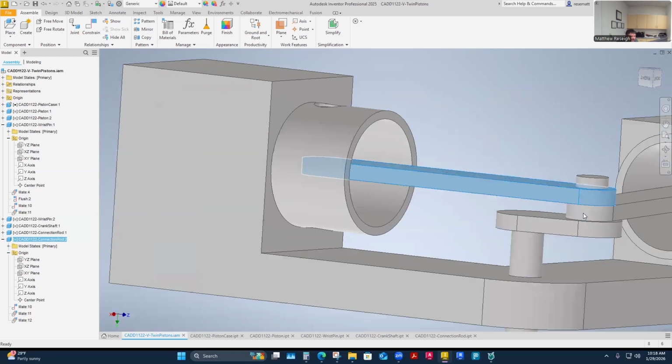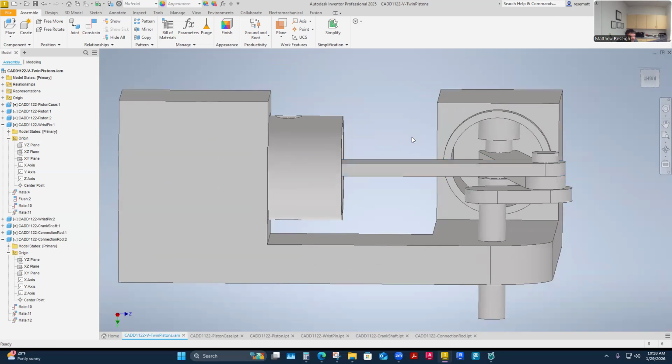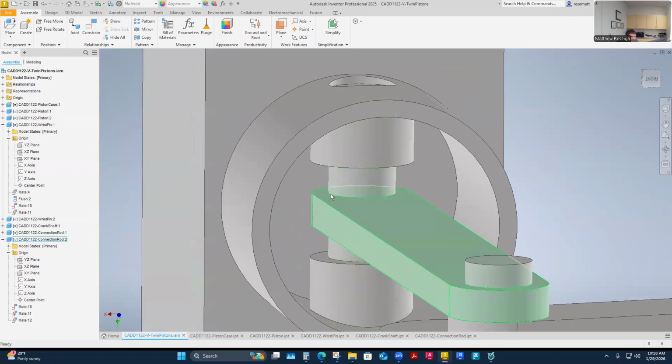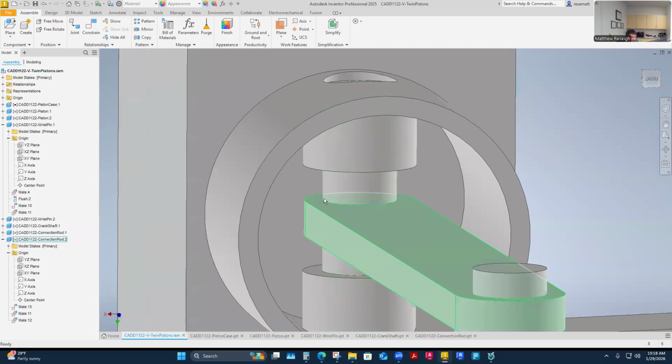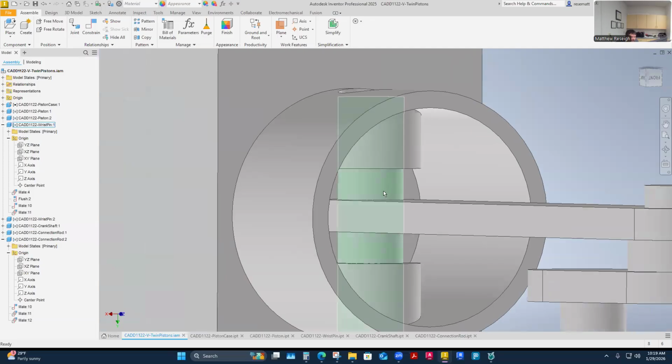And because this is like 3 to 4 inches from here to here, in the real world, if I just set this here, this thing will probably sag down and maybe get jammed up on itself. So when I looked at this assembly, I needed a little something. That's why I thought of a snap ring, because of my experience. I'll just put a snap ring here on the top and bottom. That'll hold the connection rod always centered on the wrist pin.